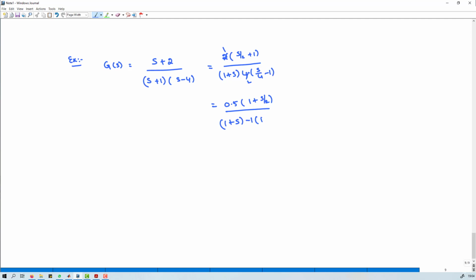So then it is in the form of 1 plus, or minus, that is 1 minus s by 4, that is 0.25 into s. You can write that even that way, or you can write directly 1 minus s by 4. So that minus 1 symbol is there. Whenever the minus 1 symbol is coming, as I told you, you have to go for minus 180. Obviously when you are finding out the magnitude, you have to find that minus 180 as a point of interest.